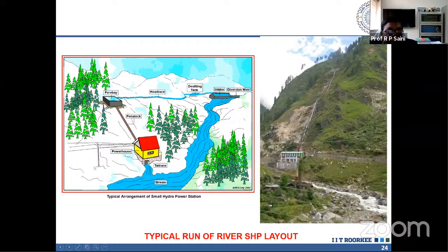This is the basis to design the volume. As a thumb rule, for the volume of this tank we consider 2 to 3 minutes capacity.